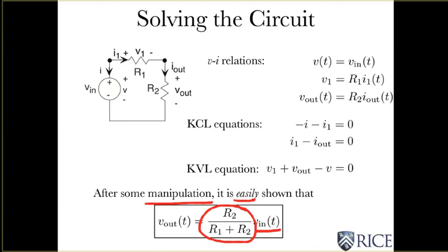So anytime you see a voltage source attached to two resistors in series like this, you'll always find that the voltage across a resistor obeys this rule. And in fact, I'm going to ask you to tell me what is the voltage V1. And I want you to do that without doing any calculations. You should be able to just tell me what that answer is. All right, well, that relationship for voltage across a series connection of resistors is called voltage divider.